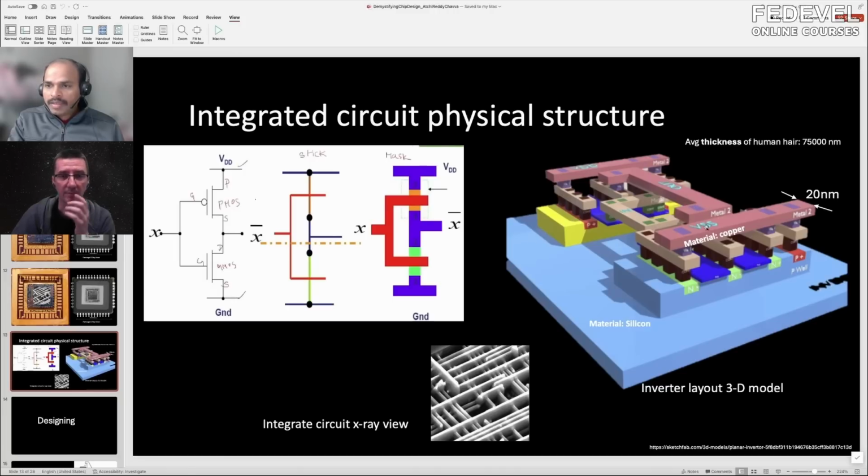Sorry for interrupting. So basically, if I understand, or maybe I may be wrong, you can build the components only where the silicon is, and everything else is kind of connection? Or can you build components also on the other layers? No, components basically lie at the base structure. What we call components are nothing but the transistors. Those are active devices. So they stay at the lower layer.